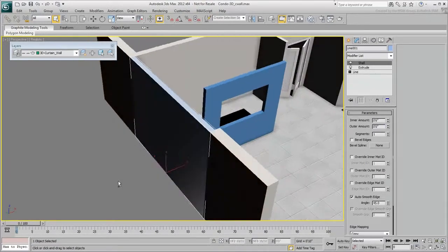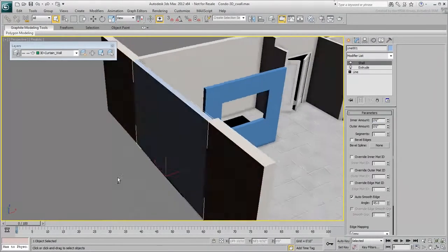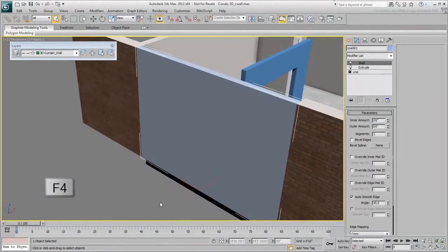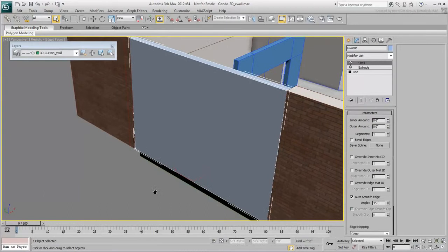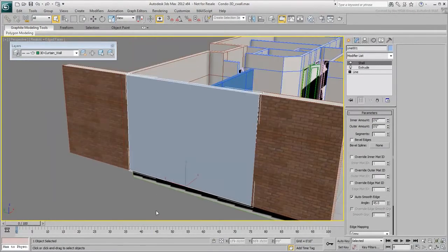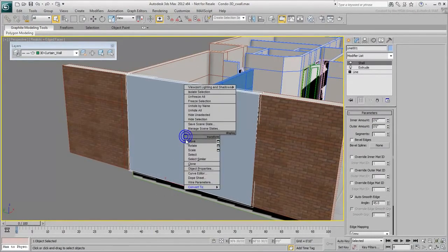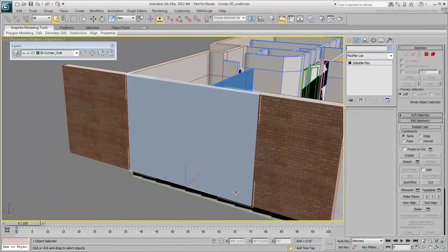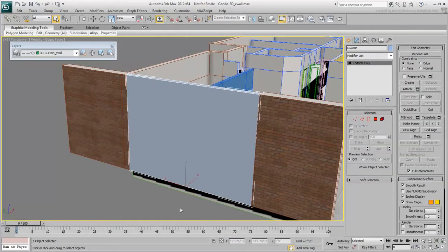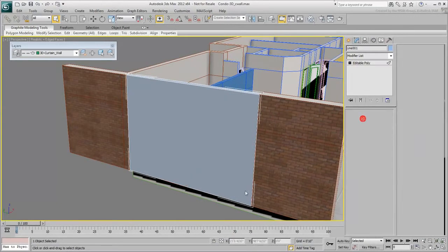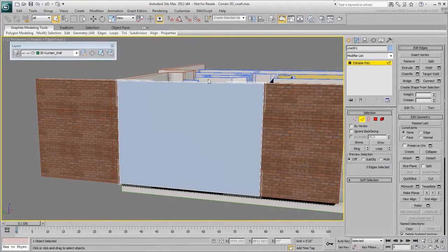You now have created what is essentially a box. Press F4 to see the underlying geometry. You could have created a box because at this point you need to collapse the object to an editable poly. Next, you subdivide the object to create mullions. In Edge mode, select all the horizontal edges. Using the Connect Settings tool, set the number of divisions to 3 to get 4 panes.